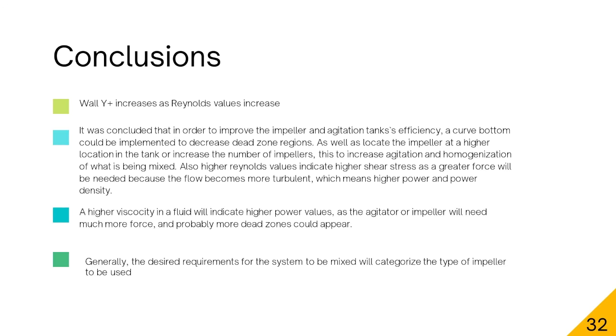Also, higher Reynolds values indicate higher shear stress as a greater force will be needed because the flow becomes more turbulent, which means higher power and power density. A higher viscosity in a fluid will indicate higher power values as the agitator or impeller will need much more force and probably more dead zones could appear.